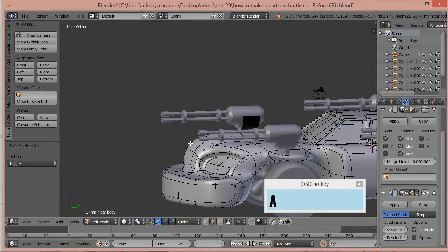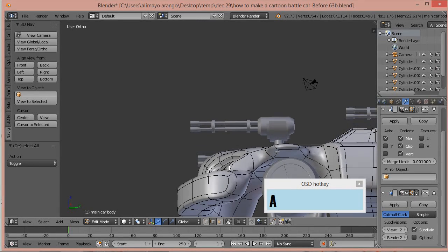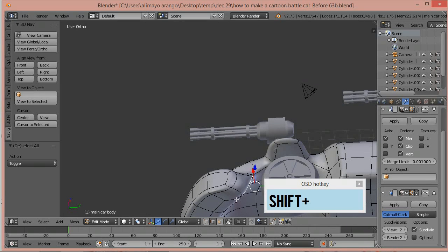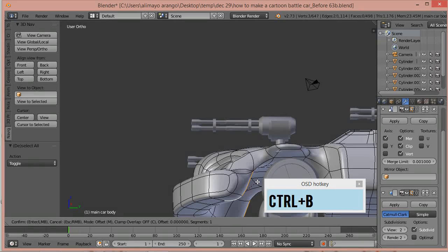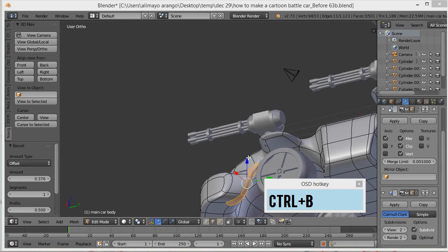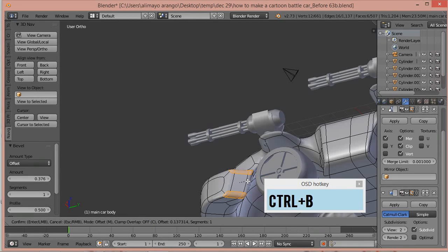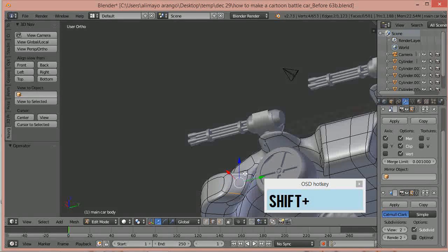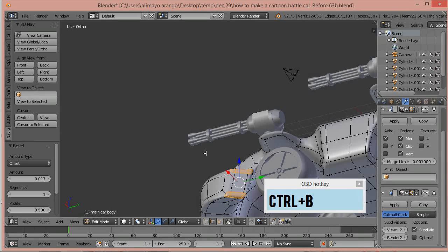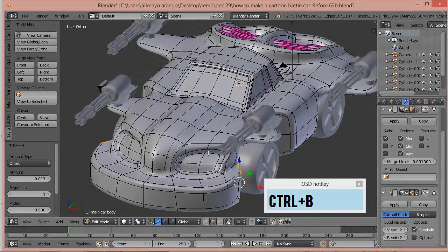The bevel's nice because it allows you to aim for specific things or specific areas and deal with them. Like, see this area right here? Let's see what the bevel does here. Select here, here. We'll press Control B. Put the bevel on it. Not quite, because we probably need this too. Let's see. Playing with it a little. Try it again. Control B. There we go. You know, just harden that right up, just putting a bevel in the right places.